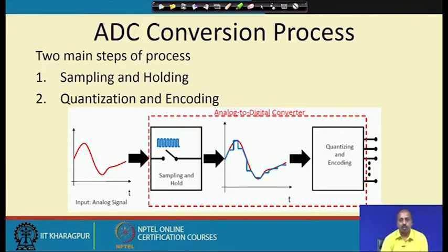I cannot design a circuit that can go on converting these analog values continually. Instantaneously it cannot convert into the value, because the circuit will have its own delay. If the input is not stable for that much period of time, I cannot convert it into any other form. Any digital circuit will require the input to be constant for some amount of time.